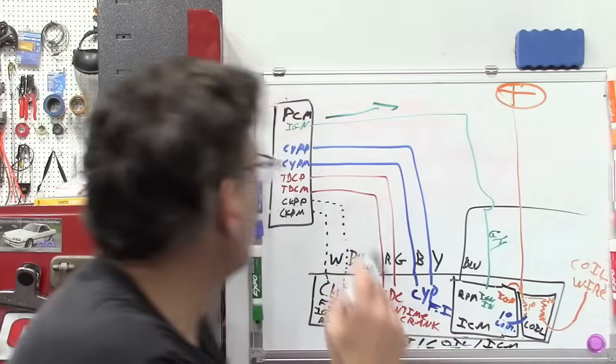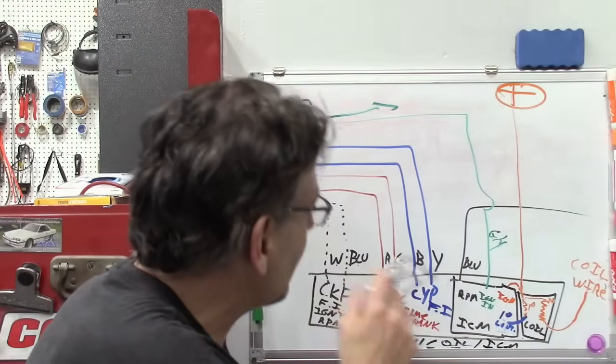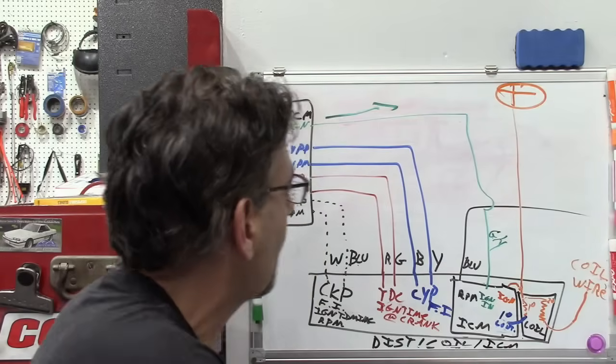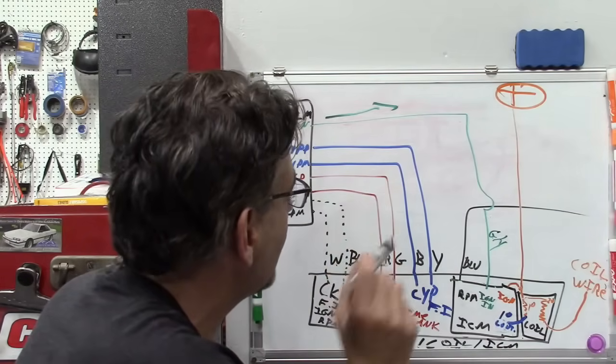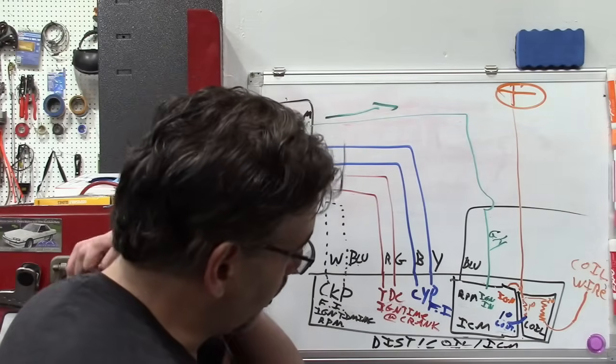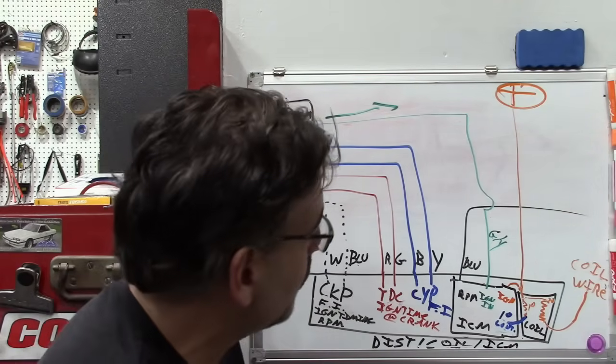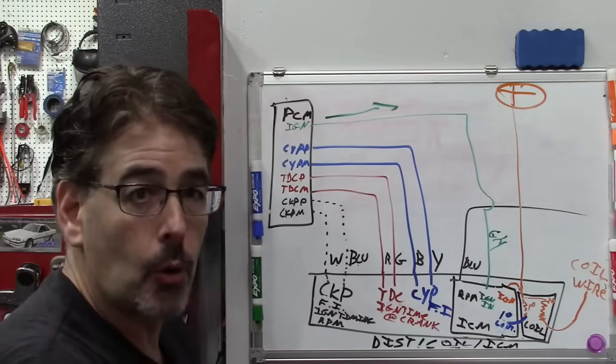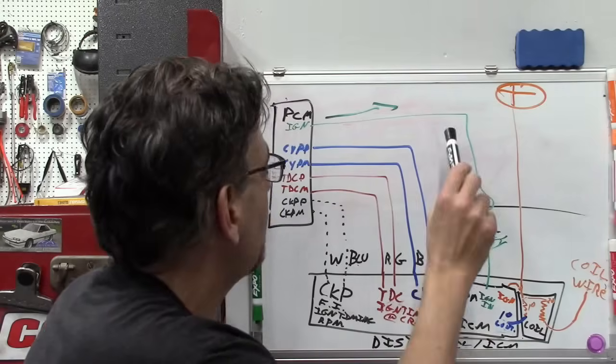All right, well, it is a little complicating now that my ignition input test there did not produce a spark from the coil, and that means there's a few more variables here, unfortunately, and not the least of which is that maybe that test is invalid because there's a little more complication. But it seems pretty obvious to me.